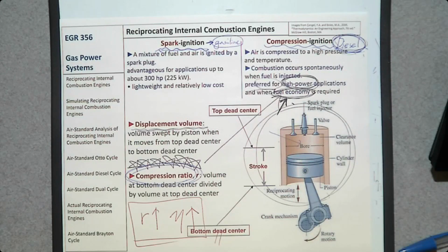That's when you have minimum volume, and when combustion occurs at minimum volume, you can produce the maximum power, right? You don't want combustion when the piston is at bottom dead center. It's not going to produce any work, right? So you want to make sure that the timing when the spark ignites the air-fuel mixture is right at this time, right?